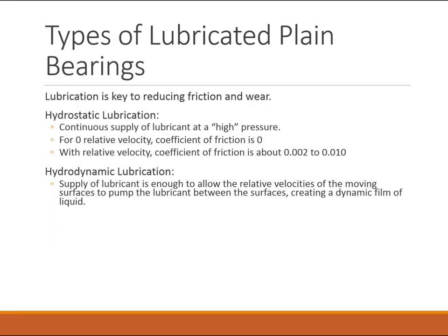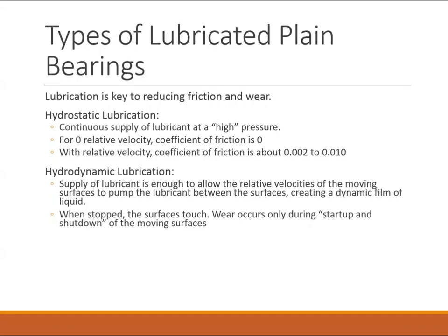Hydrodynamic lubrication is where there's enough lubricant to allow the moving surfaces to actually pump the lubricant between the surfaces. So there's a dynamic film of liquid. In other words, if I stop the rotation of the shaft, the film disappears from between the shaft and the bearing. But as I spin the shaft, I'll force a film in between the shaft and the housing.